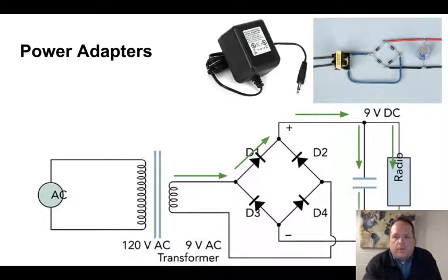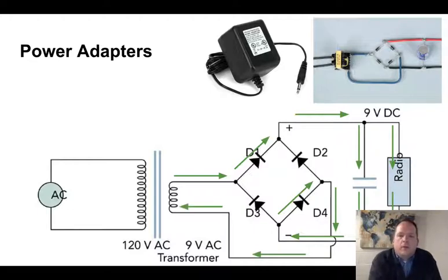Current flows off the other side of the capacitor and through the radio, and it combines down here on the bottom side of this circuit. And then it reaches a junction, passes through D4, and then back, and that little jump is a bridge showing that those wires aren't actually electrically connected, back all the way to the other side of the secondary coil.